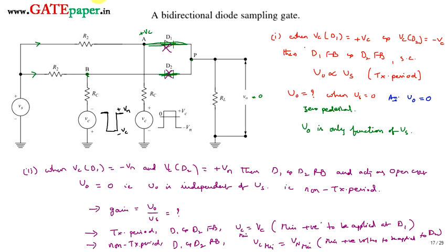And you may think that, depending on these diode directions, it can also accept positive as well as negative signals. Since the voltage we are taking as zero reference is this one, Vn is a large positive voltage, Vc is a large negative voltage. So for positive voltages, it can be passed through D1, and for negative voltage the signal is going to pass through D2 and reach the output.